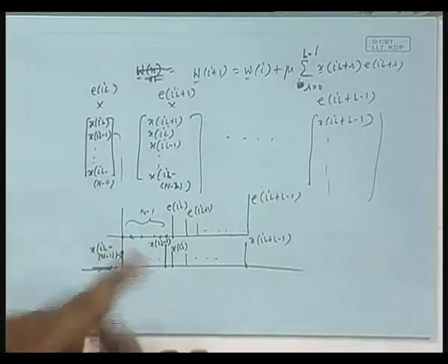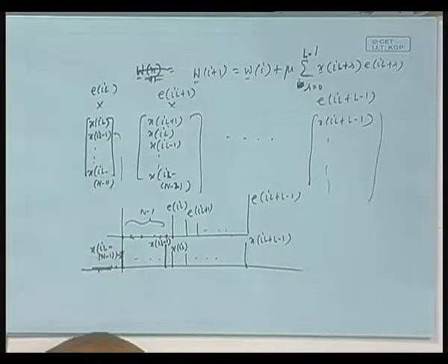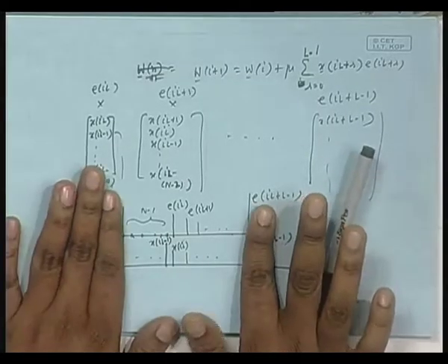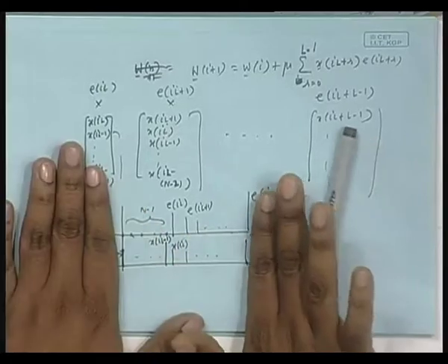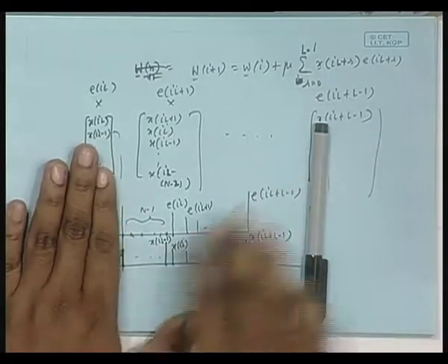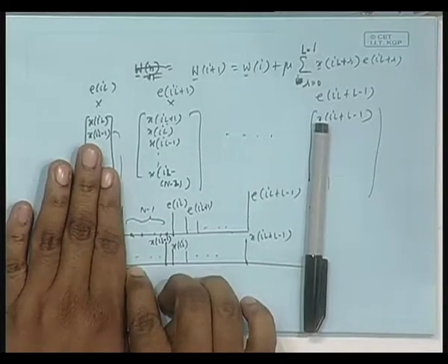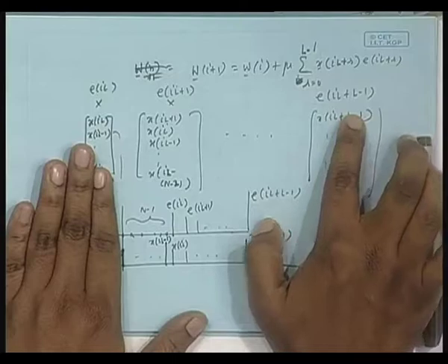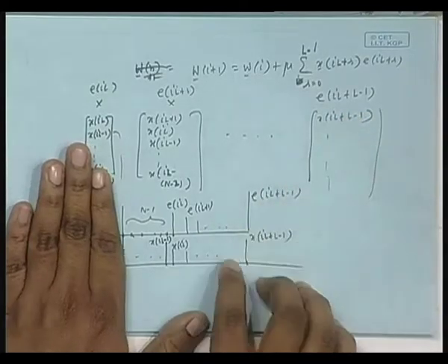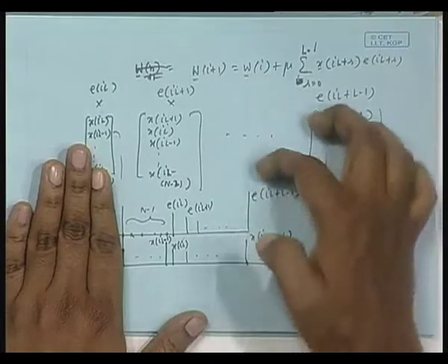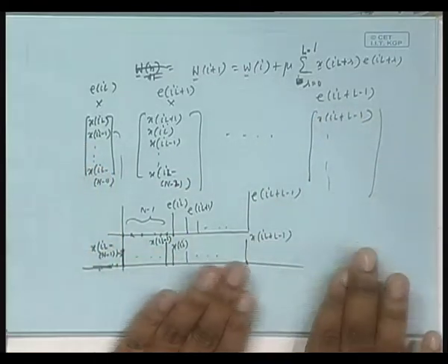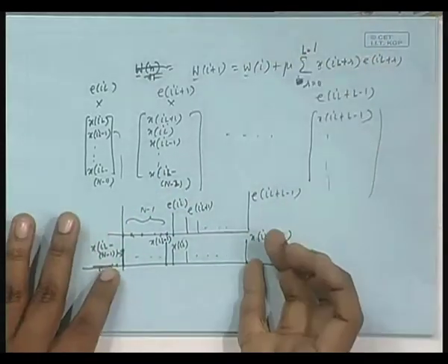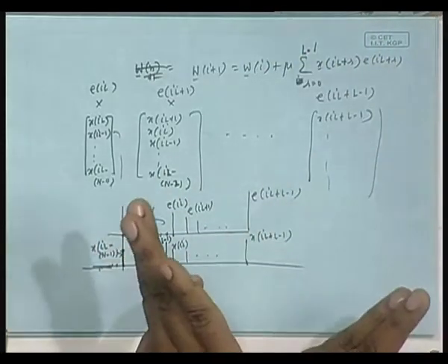Anyway, time is up, so I will just throw away this question. This is what we do in that intermediate stage of circular convolution. First, no shift, multiply, then shift by 1 bit, but chop, confined within this only. From here, if I send in a 0, that 0 comes in, one data goes out, this fellow comes here, this goes out, the previous fellow comes here, and again you multiply, add, and go on doing it, isn't it? That is what we do in circular convolution at the later computation stage. So, that means this is obtained by reversing something.